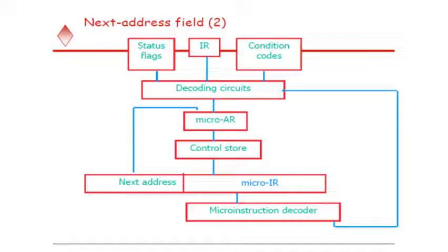Let us now reconsider the example of the microinstruction flowchart which we have seen previously. Using the microprogram control structure, we need several control signals that are not included in the microinstruction format. Instead of referring to registers R0 to R15 explicitly, we use the names RSRC and RDST, which can be decoded into actual control signals with the data in the SRC and DST fields of the instruction register.